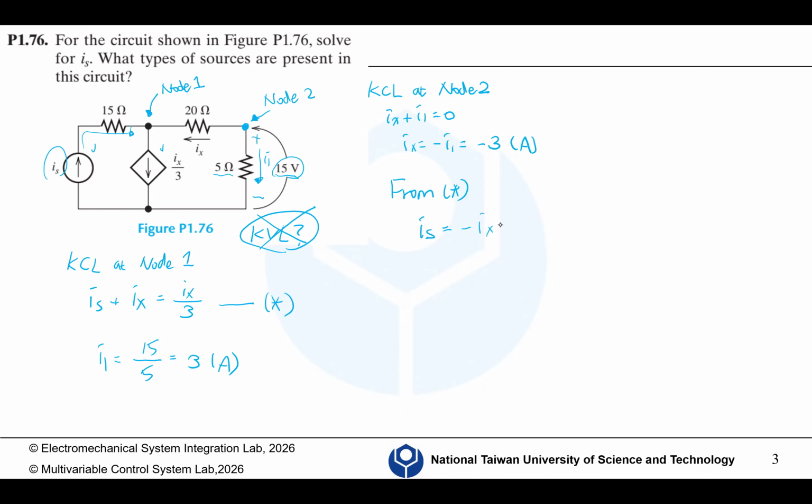So KCL at node 1. Yes, we use nodal voltage analysis, but we apply KCL because we need to convert the current to a function of voltage variables.